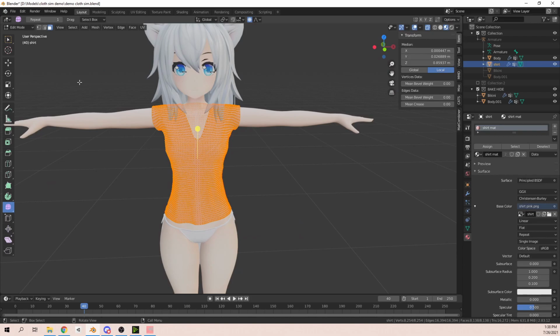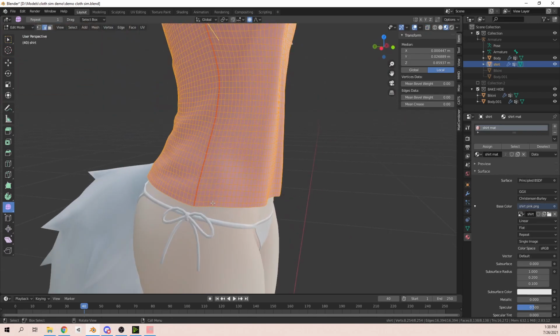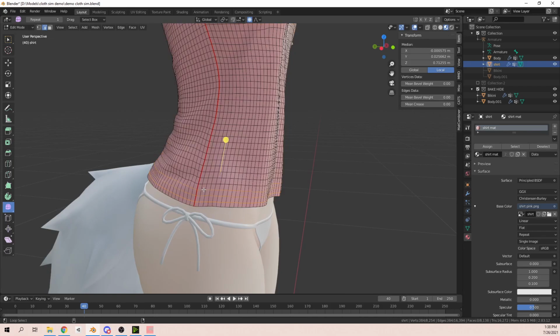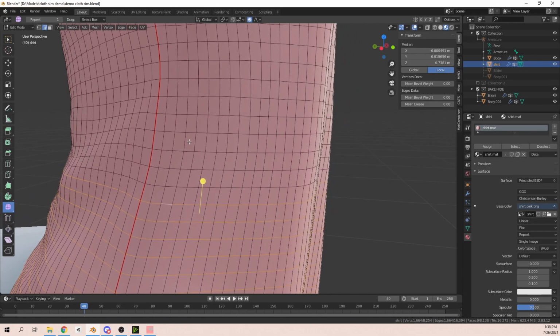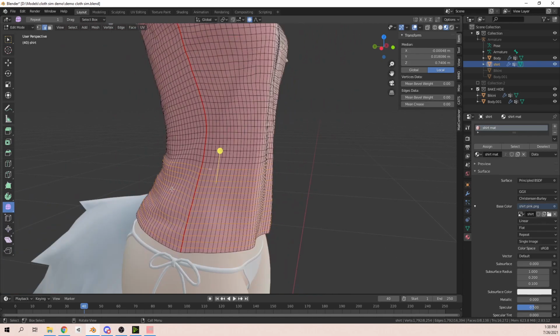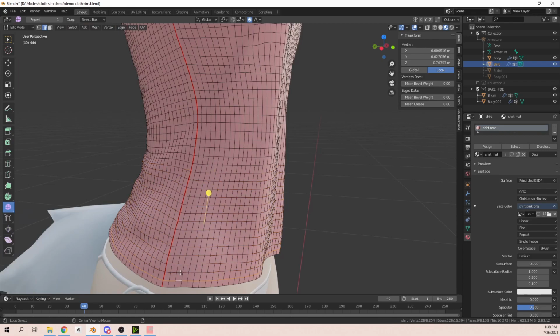Pretty high poly, and we wanted high poly at first during the bake, but we don't necessarily need it. So luckily we worked with quads, so we can just start dissolving edges. So I'm just pressing shift and alt. Use discretion where you actually want to dissolve it. Also, I'm doing every one, so I'm doing this wrong. So use discretion, unlike me.